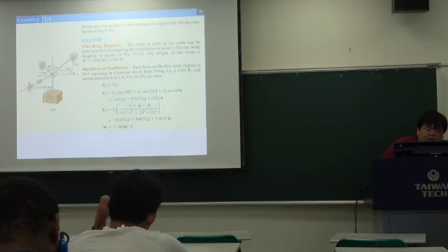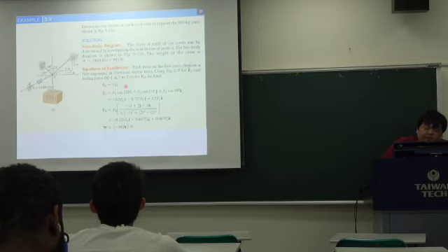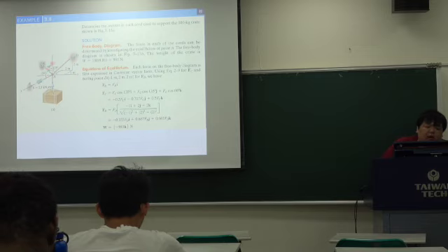Okay, so we can do the equation of the equilibrium. The FB at the x direction, so just FB is equal to FB times i. Then FC, we use the angle between the FC to x axis, y axis, and z axis.